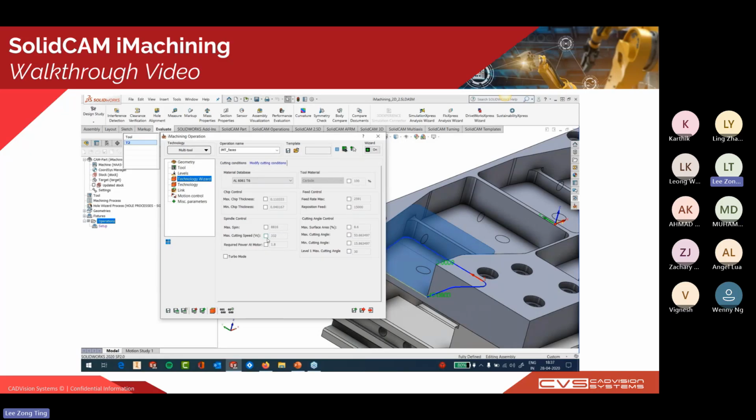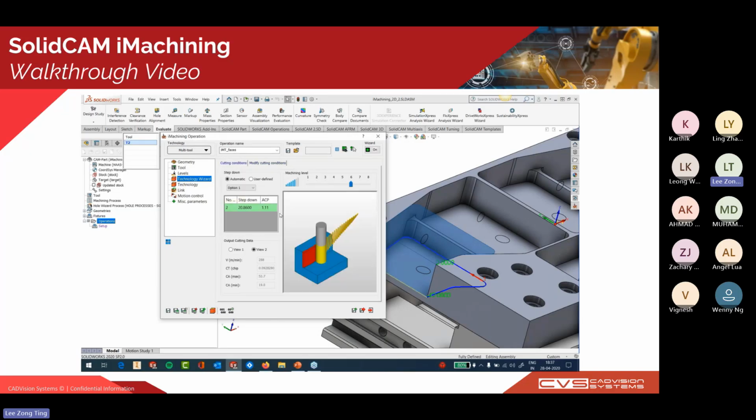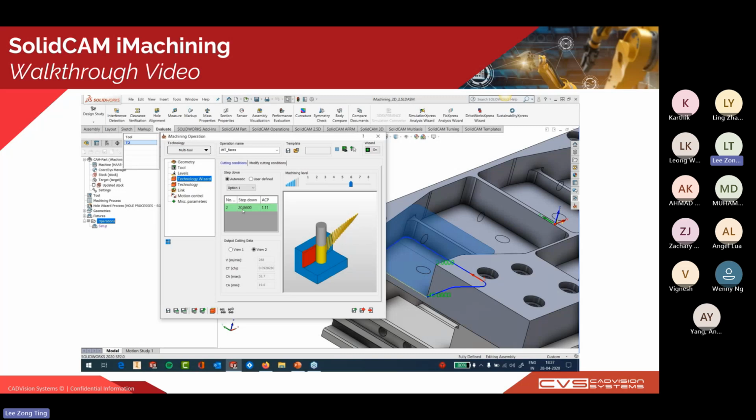But in the modified cutting conditions here, all these values are already calculated for you. You can see the maximum cutting angle and the minimum cutting angle. If you want to change it, you can change it in the cutting conditions, and it will automatically recalculate the spin rate and feed rate for you. Later on we will see how we can change it.